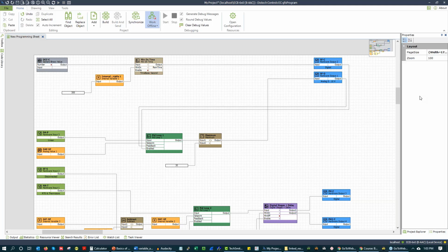Can block programming be converted into code? So it depends on the software. Block programming can kind of sort of be converted into code in Workbench. You can actually move between Java and not Java. If you go through the developers training that Niagara puts on, they'll teach you that. I don't know why you would. KMC does that natively. They support switching between graphical and line code. But I don't know why you would, because that really precludes you from being able to work with the market.